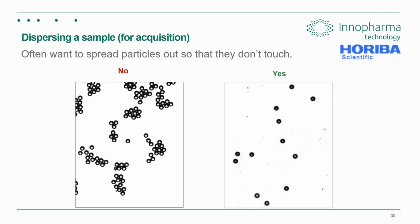So if we talk a little bit about dispersing samples, that can be a consideration for particle size analysis. You'll often want to spread the material out. Let's say we're looking at a binary image here, a black and white image on the left, and the materials are touching. It can make it a little bit more difficult for image processing to define those edges. So you might have to put the image through some more filters and steps. Watershed is a good tool for separating joined particles.